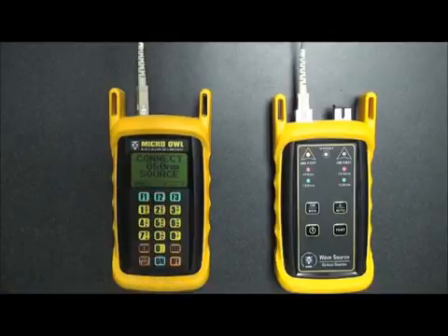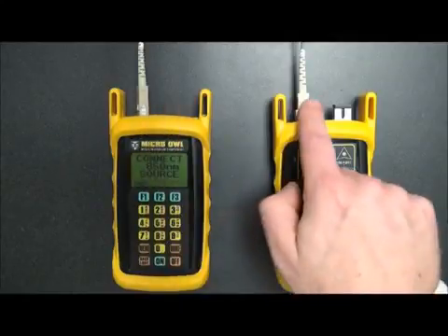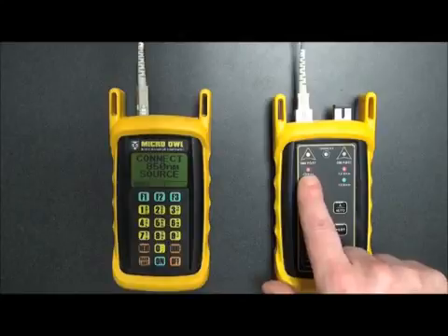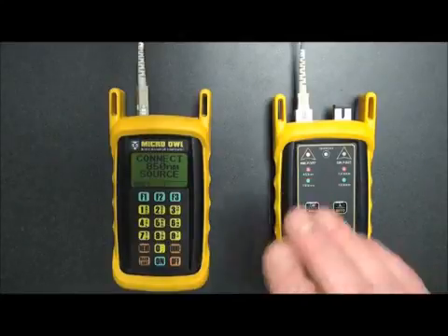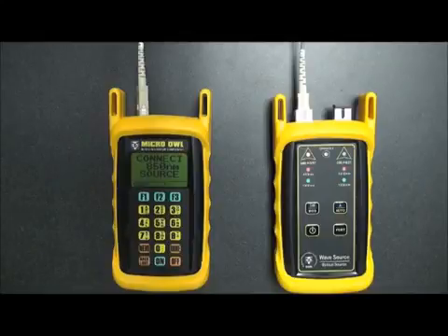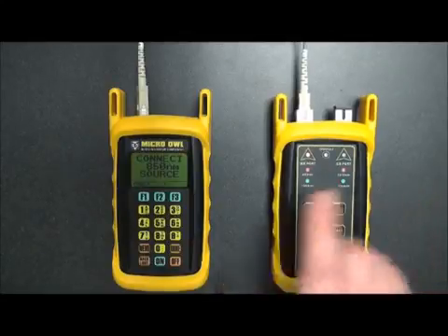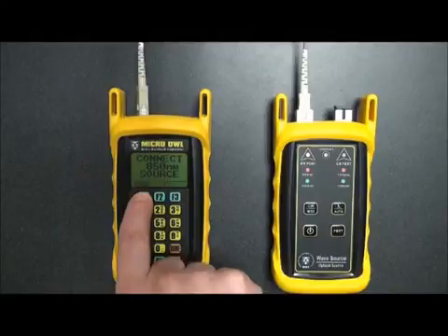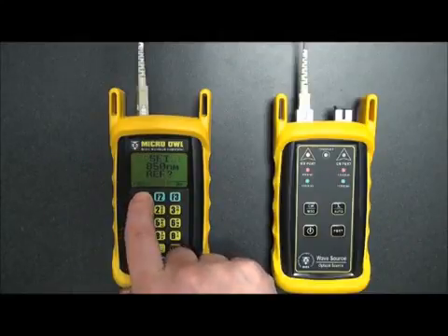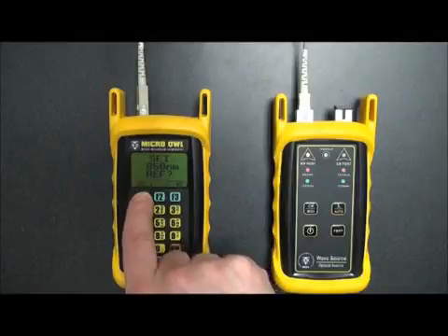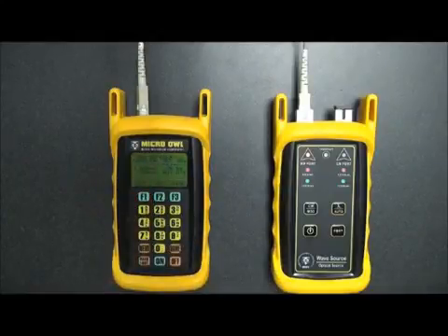And now the meter is going to ask us to connect our 850 nanometer source to our meter. So as you can see, the patch cable is already attached. The multimode port is active, and it says 850 nanometers. So we are connected the way we need to be. Once we've verified that, we simply press F1 to confirm. And then just a fail-safe asks us to reconfirm, just to make sure that we've actually got everything connected right. Press F1 to confirm and save the reference.